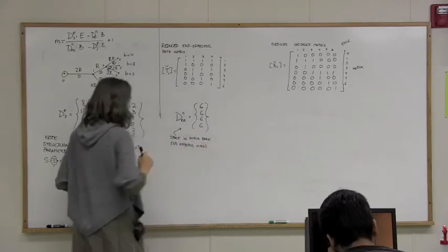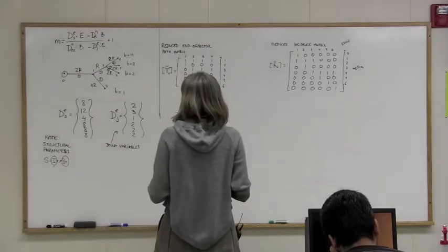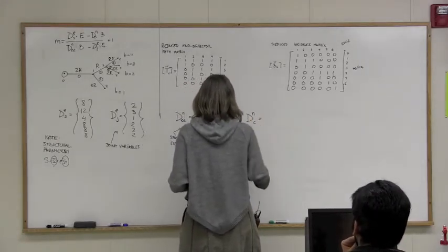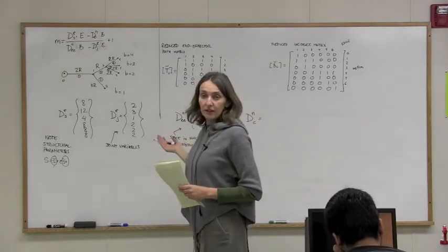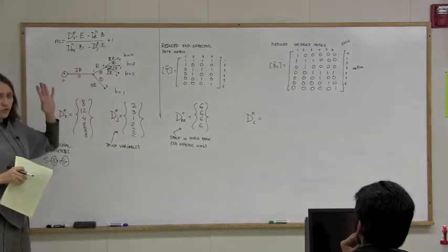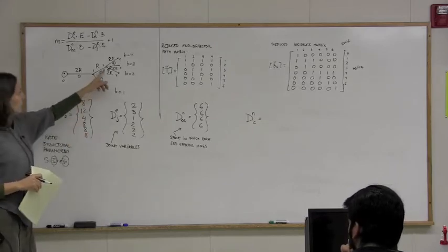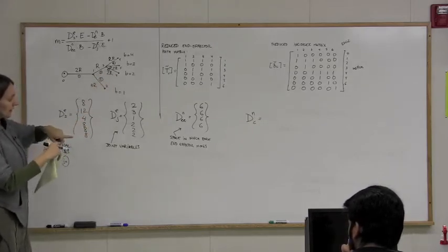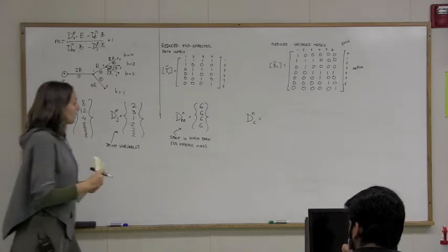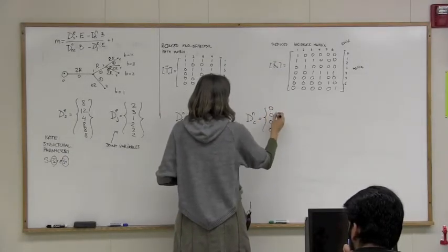Okay. And then the last one, which was the DNC, right? DNC. And that was the extra constraints. In this case, we just don't put any extra constraints. You could say, but I want these 2 revolute joints to be parallel or perpendicular to mimic more like a wrist. Or I want each finger to look like a human finger, so the joints have to be parallel. In this case, we just design a general hand or a general tree structure with no conditions, which means 0 extra constraints for each of the